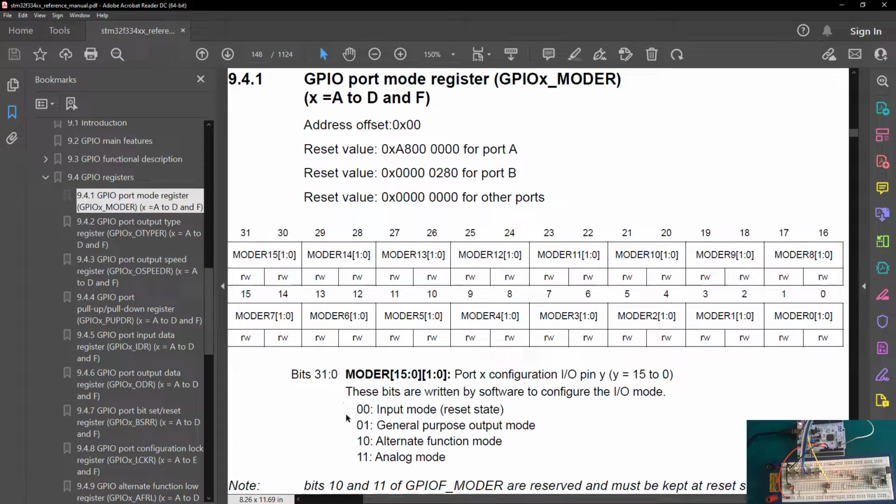Now if you just write 01 into the whole register, it's not gonna work. You'd probably just be writing the first bits here. Now you have to assign 01 on all of them, and that's going to be a large number. No, we're not gonna do that. So we're only going to take the selected bits, the selected pins that we need. So that is pin 4, 5, 6, 7, and 8. 5 pins on GPIO A that need to be used as output.